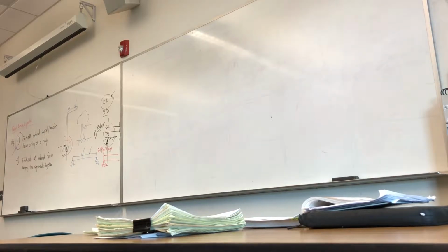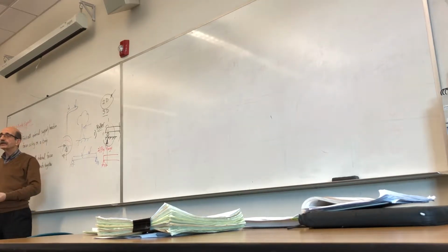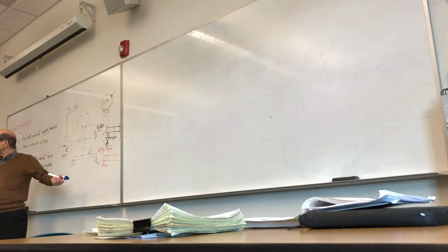If you look from the top, just from the top, so take this cross section. The motion in that plane is allowed rotationally, right? But you cannot push this way, and you cannot push it that way at that joint. So motion in two directions is prevented. We call that a pin. A bolt is a pin connection.